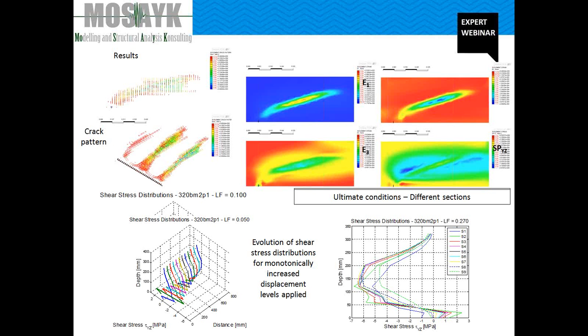The principal tensile strain directly governs the failure mode, and the presence of a variable inclined strut-tie, whose width and inclination angle evolve during the monotonic analysis, is clearly evident. Tie width reduced as the imposed vertical displacement increased, reproducing the actual shear stress flow, characterized by peaks at the bottom side of the cross-section rather than at the level of the centroid.